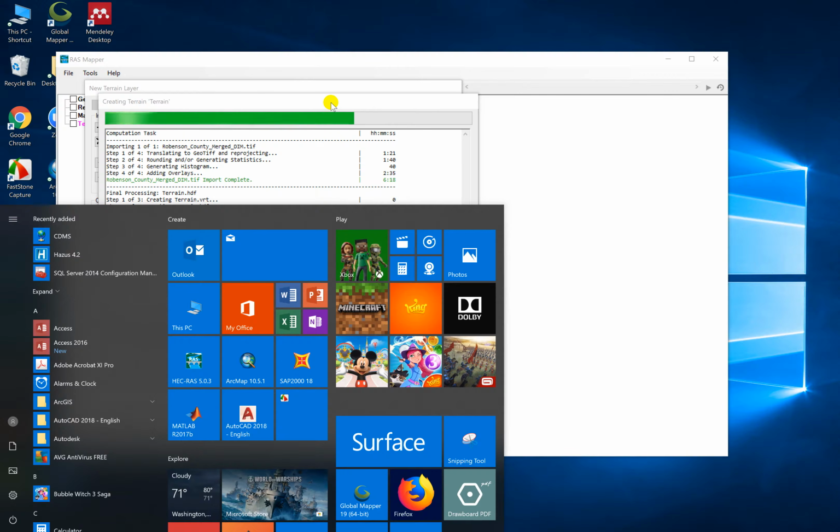So you can go from this point. I'm going to assume that I'll have a precipitation of 20-inch and then go to HEC-HMS using this precipitation to get the hydrographs, and use these hydrographs in HEC-RAS to get the floodplain. So this is the process. You can start with the precipitation, HEC-HMS, and HEC-RAS.